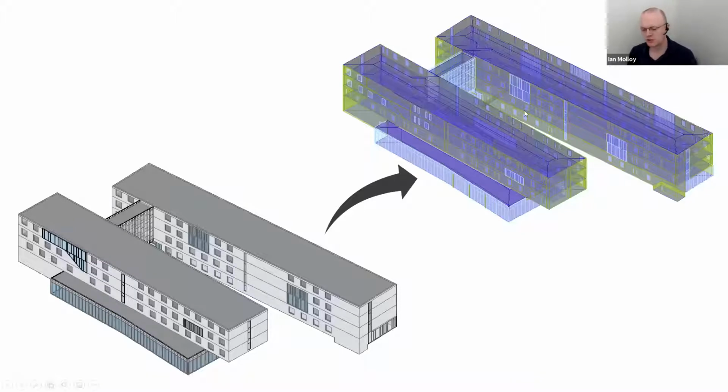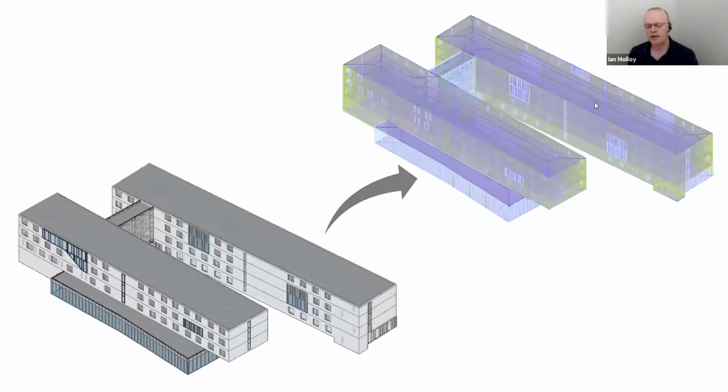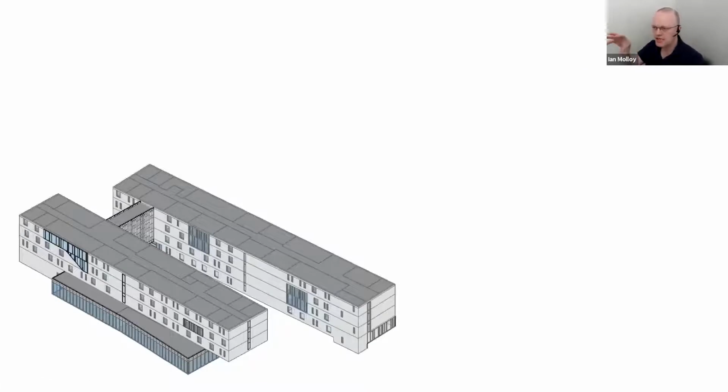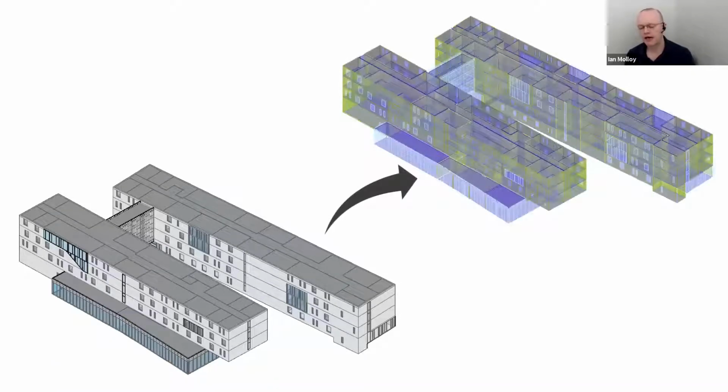Notice it's still doing perimeter-core zoning here. And then the next level of detail beyond that, remember, these are just example steps in a process where you get different levels of detail, this is about as detailed or precise or accurate as a typical energy or HVAC loads and sizing model will get you, right? Where you see the way it's broadly zoned. And we've got the window layout design, and you'll see again, the analytical model will essentially give you a one-to-one copy of whatever that level of detail is, right?